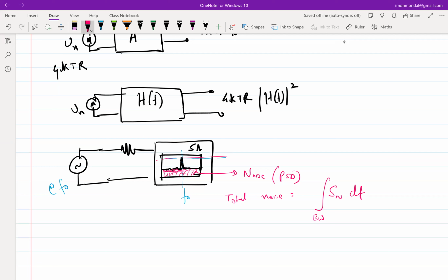If let's say you do not want to open up the channel, and you open up the channel and you do not use the full channel to send your signal, right? Then obviously your signal to noise ratio decreases. But let's say I open up the channel and I use the entire channel to send the same signal multiple times. Let's say my signal bandwidth is 1 kilohertz, but I have opened up a 1 megahertz channel, right?